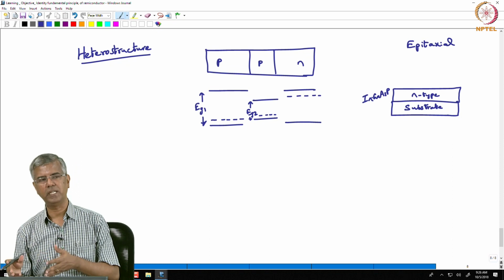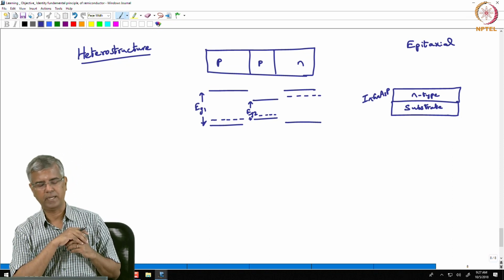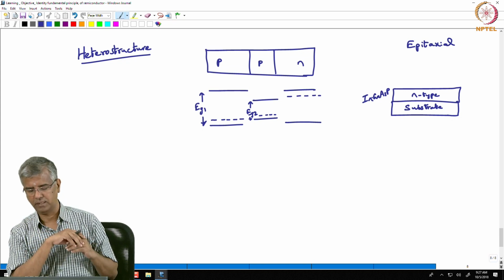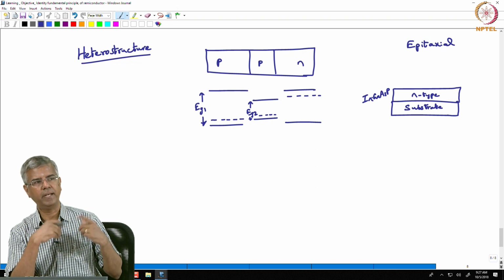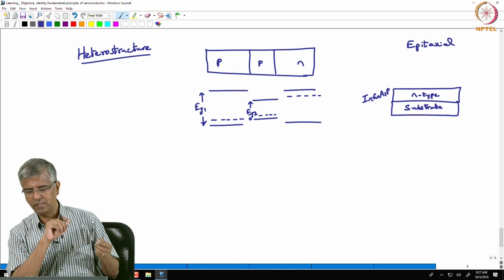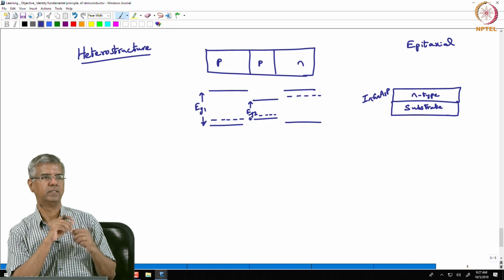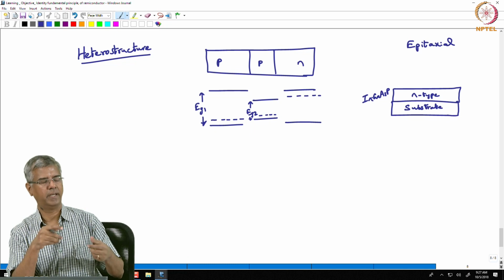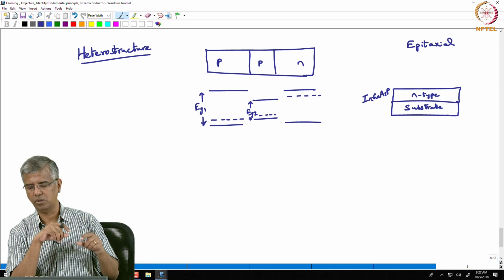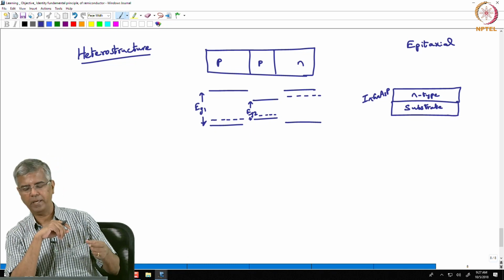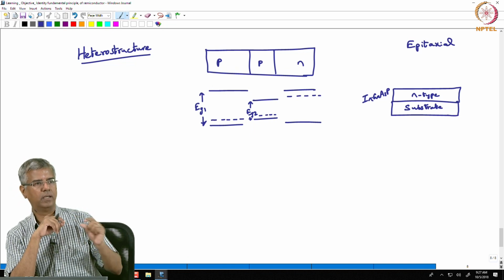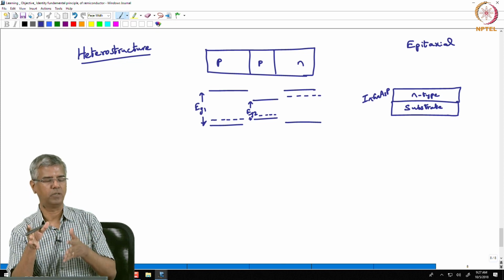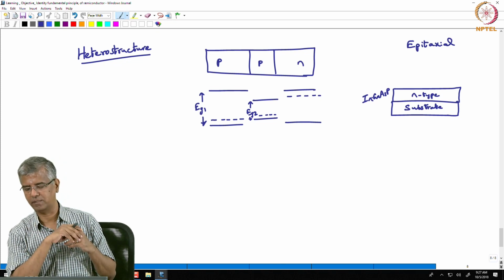Okay. So you initially start depositing indium gallium arsenide phosphide to make that n-type layer, and then you change the gallium and arsenic concentrations, and of course the corresponding dopants also, and then you get a p-type layer but with a different band gap energy. Okay, the proportions we are not going into the details, but that's just the idea, right.